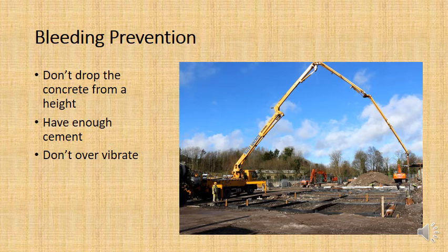How do we compact concrete? Well, one of the key ways we often compact concrete is we will vibrate it. We will place a vibrating rod inside the concrete that's been poured, and that will shake the concrete so that it falls down into the mold, and that will take away all of the voids. And so we use vibrators a lot in construction engineering for concrete technology.